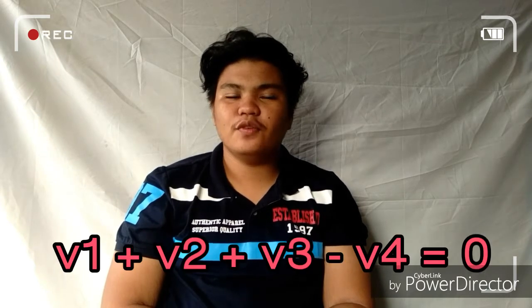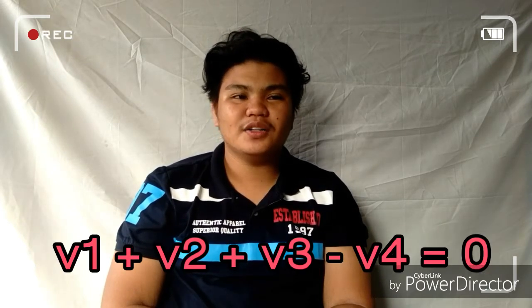The second law, which is Kirchhoff's voltage law or KVL, is also called Kirchhoff's loop or mesh rule. KVL states that the sum of all voltages around a loop is equal to 0. In analyzing a complex circuit, one can either do nodal analysis using KCL or mesh analysis using KVL.